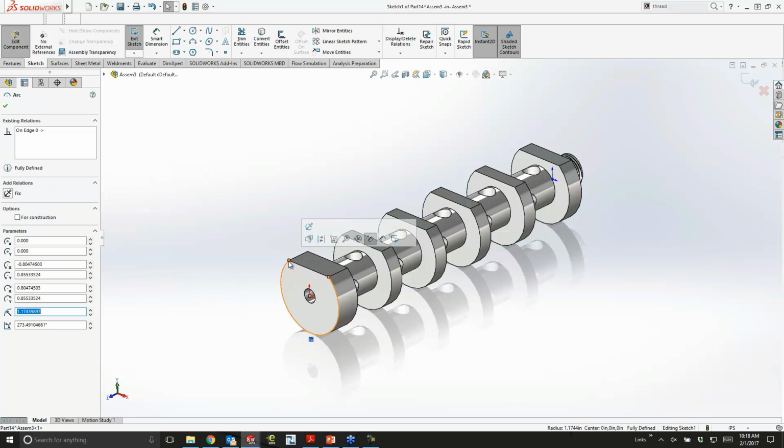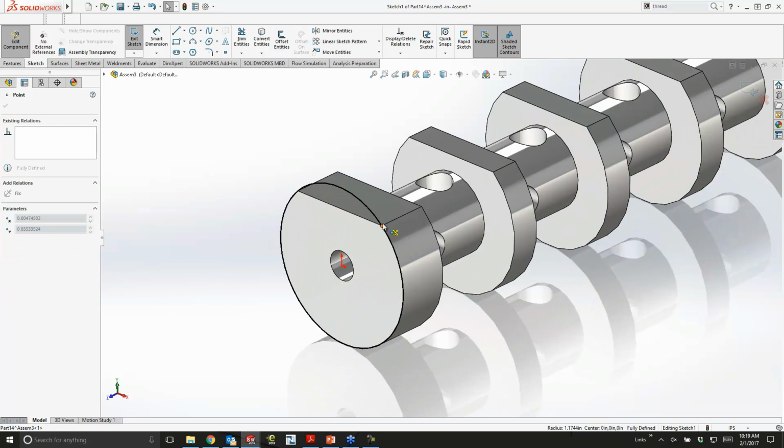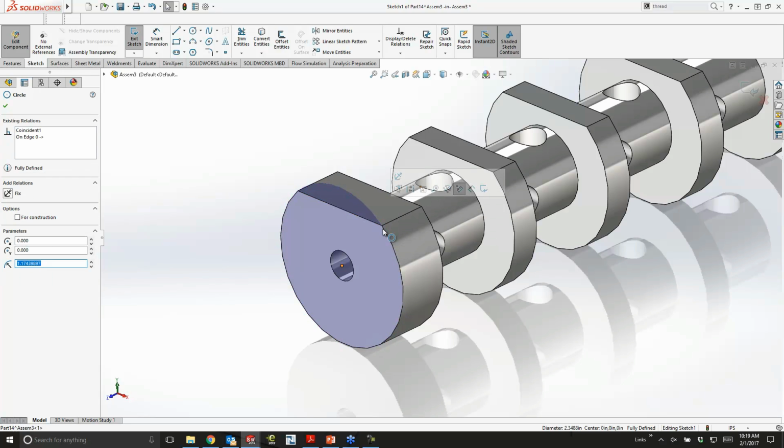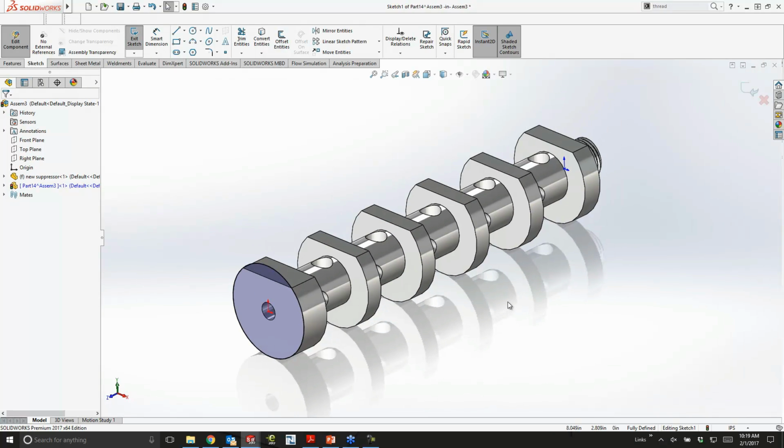And when you convert the edge, if it's an arc, which this one is, this is just a broken circle, you can just drag that arc around, and the arc endpoints connect, and it creates a uniform circle with no endpoints to it, although you still have that point available to allow you to connect to it or define its position.